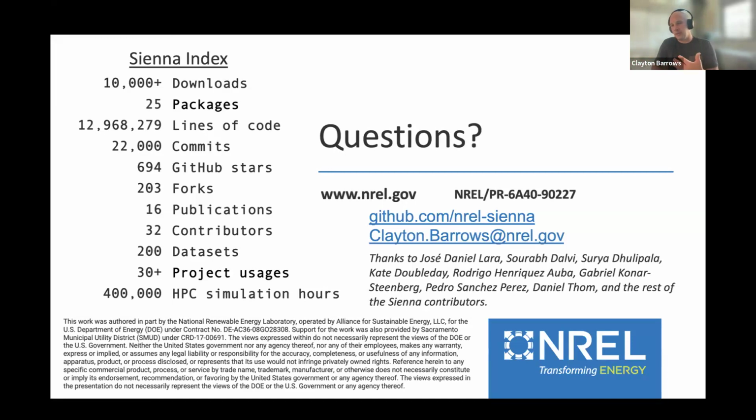Additionally, another aspect of the challenge is that the modeling paradigms are quite different, especially between scheduling and dynamics, where you're moving from an optimization paradigm to a dynamic system of differential equations paradigm. And so there's still an overlap, in that the initialization results are based on the scheduling decisions that are made. And so we now have modeling capabilities where we can populate the initialization of a dynamic simulation with the results of a load flow problem and things like that.